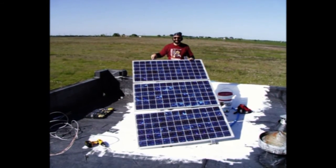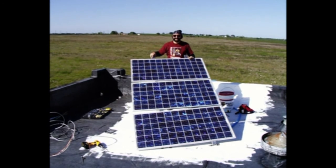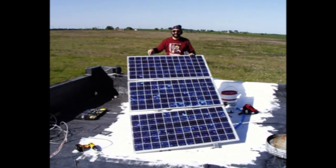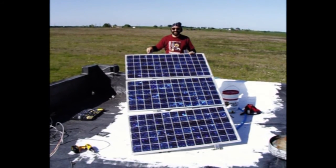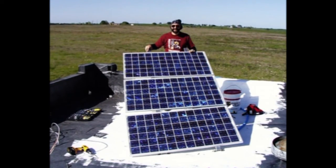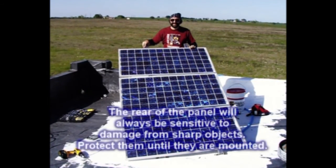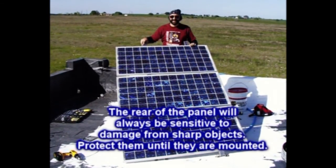Your solar panel frame itself, the aluminum frame, is not very strong. It needs to be supported by a substructure or another frame, and we'll talk about those types of frames later in the video, but handle them carefully before they're mounted. And the rear of the panels will always be sensitive to damage from sharp objects, so always protect the rear of the panels.